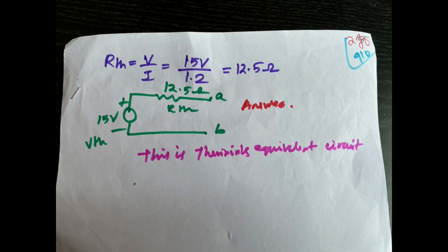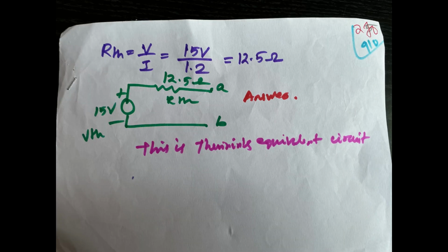Then Thevenin resistance is VAB open circuit voltage divided by IAB short circuit current. In the short circuit, the 6 ohm is dead resistance and the 0.2 is a 0 source. From the VAB and IAB values, find the RTH value. From the RTH and VTH values, form the Thevenin equivalent circuit.